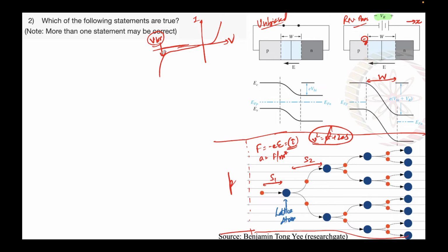what you can see is that at a certain breakdown voltage, why is this important? Because this breakdown voltage plays a role in the depletion width w. Just recall your expressions, because w also has a square root dependence on VBR. We'll see in a couple of slides later that that is the case. So if VBR is large enough, your W will be large enough, and your peak electric field will also depend on that. Because if we know the peak electric field, or the Emax, it was ND times Xn, directly proportional to this, the magnitude of it.